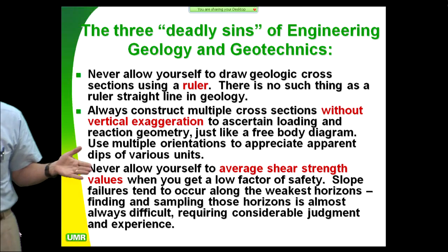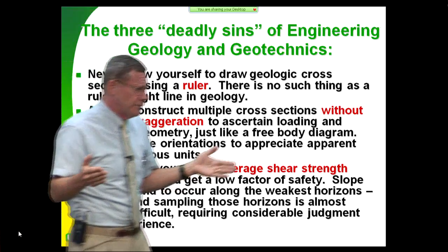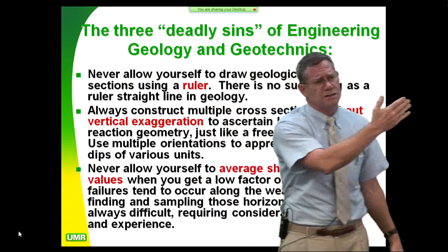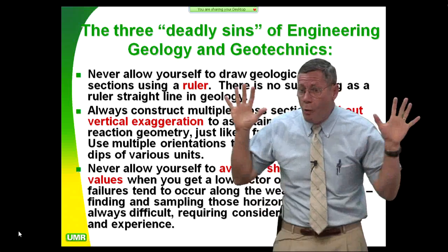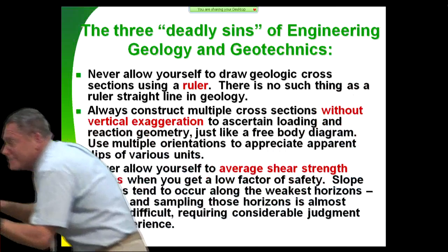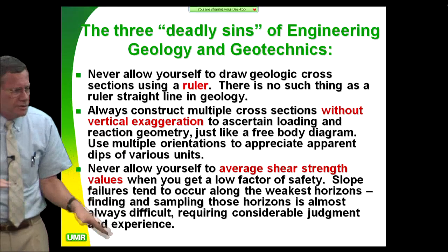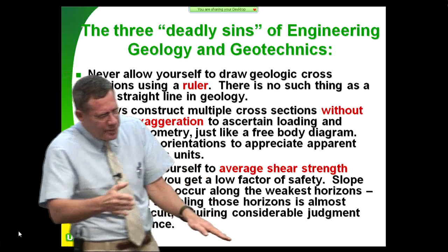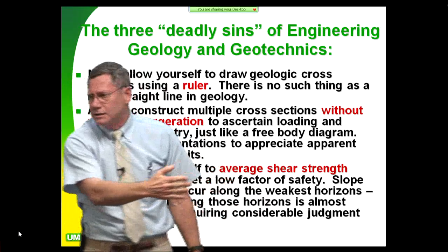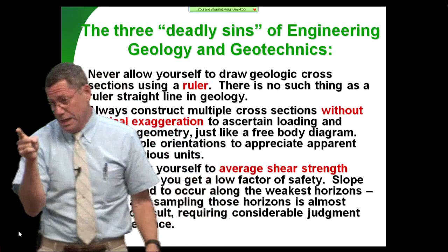It's like looking at a seepage analysis on a levee. If you go into the Corps manual, the office manual for levees, they always have the seepage cross-section 90 degrees to the levee. So all the water in the world is only supposed to seep under levees going perpendicular to the axis of the levee. Never does that. Ever. Ever. Go out and look at a map. Channels going like this, they build levees semi-parallel to the sinuosity of the channel. Those old channels are cutting under the levees at acute angles. And when you do the seepage analysis along the line of seepage, you're going to get a different answer.